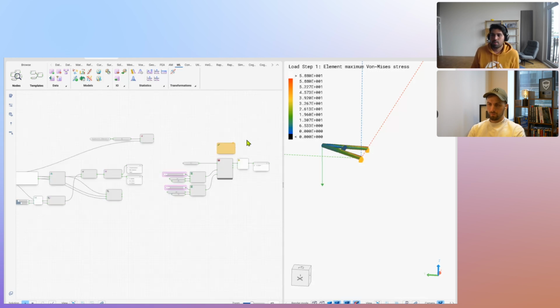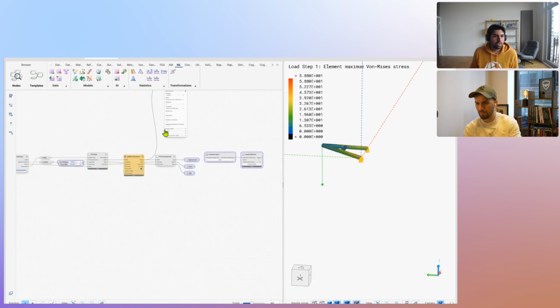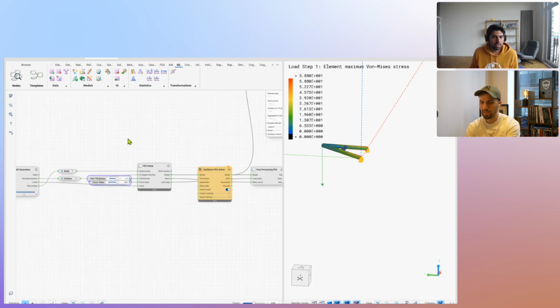I really appreciate it, Ram. Super insightful. I was wondering regarding the mesh sensitivity study, because you're training the model based on a random mesh, right? Would you do a mesh sensitivity study before you actually use it as training data, before you build the ROM? How would you approach this?